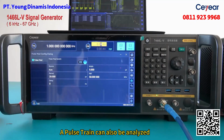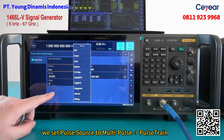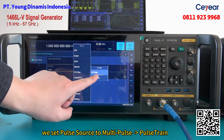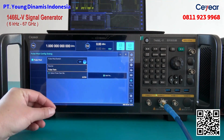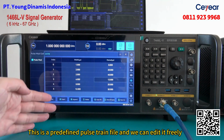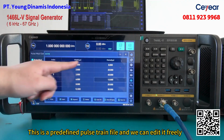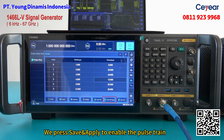A pulse train can also be analyzed. In the signal generator, we set the pulse source to multi-pulse, a pulse train. This is a predefined pulse train file, and we can edit it freely. We can see there are 6 pulses with different widths and periods. We press Save and Apply to enable the pulse train.